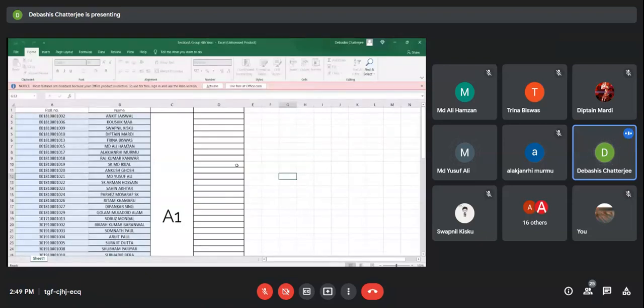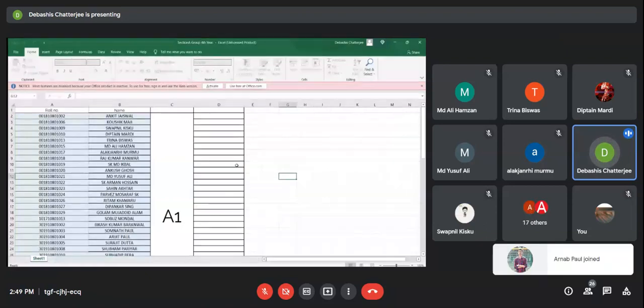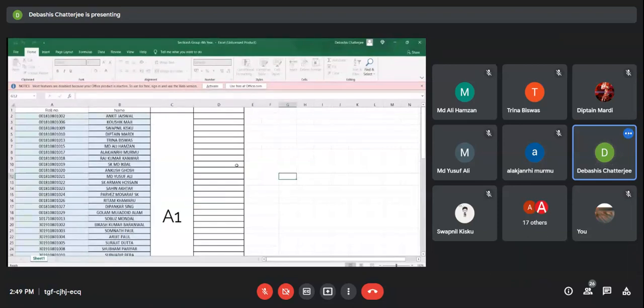Then I can help you do further steps, or if you feel some problem, we'll discuss. So you design the same machine as the first group. This is a three-phase induction machine, 3-phase 110 volt, 50 hertz, 750 watt, 735 rpm, power factor 0.8, tentative.